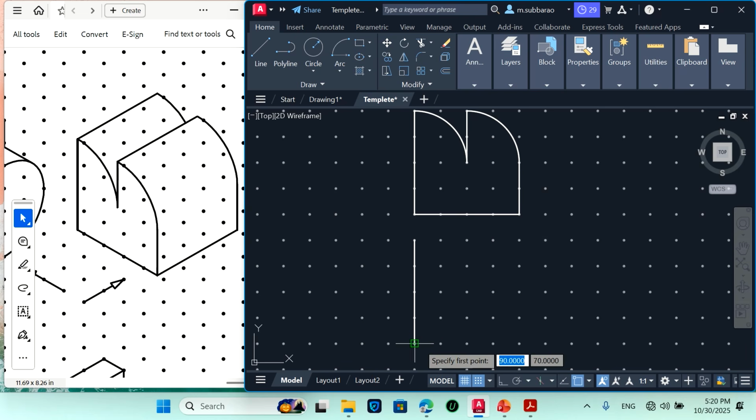So I will draw a line here, and there is one more boundary, and this is another line which is actually coinciding with the below line. So this is another boundary of the curved surface, and this is another boundary of the curved surface. So this is how I complete this, and this is also a curved surface, and this a principal surface till here, and then this is a curved surface, this becomes another boundary. So I will draw and complete the curved surface in the top view. So this is how the top view will appear. So this curved surface will appear like this, and this curved surface will appear like this.